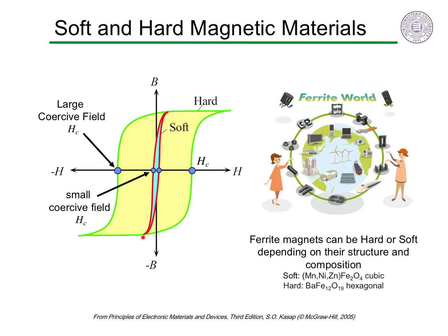Magnetic hysteresis loops can be wide or narrow. A hard magnetic material has a wide hysteresis loop because of a large coercive field, which is needed for a strong permanent magnet. Hard magnets usually have high magnetocrystalline anisotropy to keep the magnetization along a particular crystallographic direction. Also, because defects and microstructure pin the domain motion that would demagnetize a magnet, the hardness of a magnet depends on the composition, impurities, and processing.